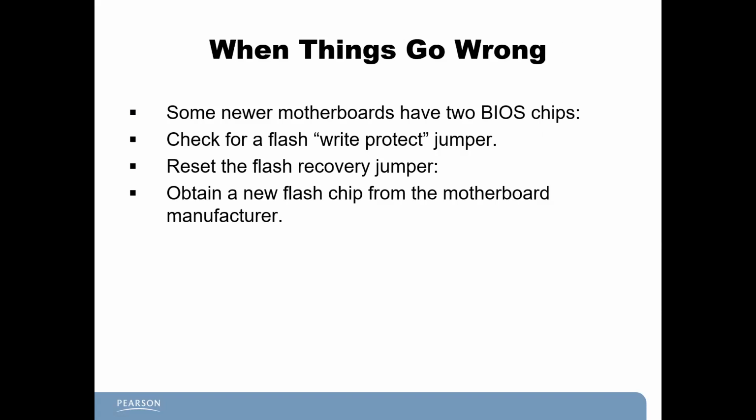When things go wrong, some newer motherboards have two BIOS chips. So reboot using the alternate BIOS chip if the new BIOS upgrade fails. Check for a flash or write protect jumper. Reset the flash recovery jumper.